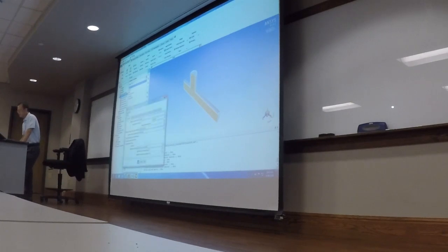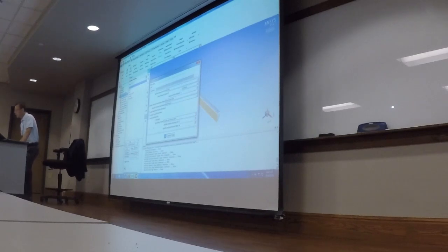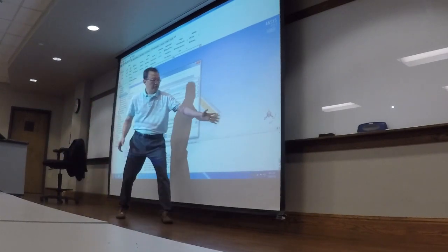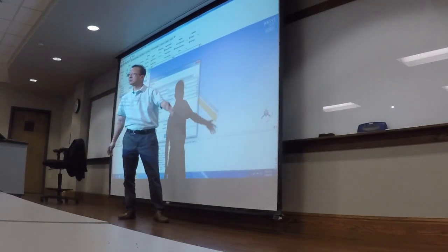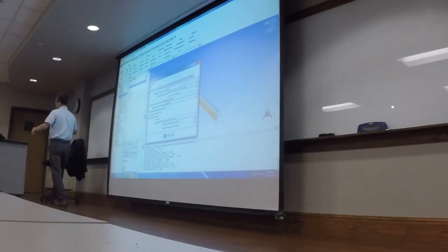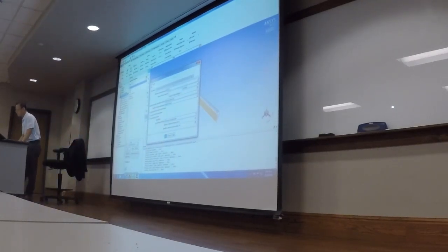Change the type to pressure outlet. Exit 1 is pressure outlet. And here, we put the pressure as 0, which means after this T-junction, water exit 1 will go to ambient. Here at top, same thing, go to ambient. We put the pressure as 0.